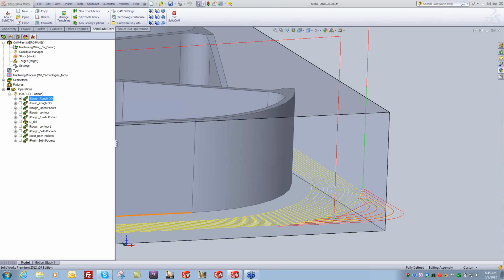All right, John, how do I get the diameter symbol? Okay. That is, and hopefully this goes out to everybody, holding down the Alt key plus the number pad, not the numbers above your QWERTY keyboard. It has to be a number pad. You're going to type in 0216. Okay, 0216.